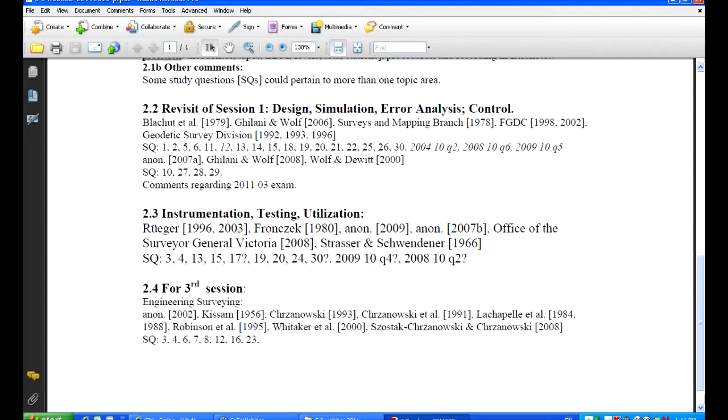And if we go into Ruger's discussion of the design of a baseline, he offers several formulas. And if we look at the ISO specifications for coming up with the variance of a distance, there is a reference to what's referred to as the Heerbrugg formula, which basically gives us a way of calculating the spacing between the points if we were to set out this linear array in a way that would allow us to sample different portions of what's referred to as the unit length.